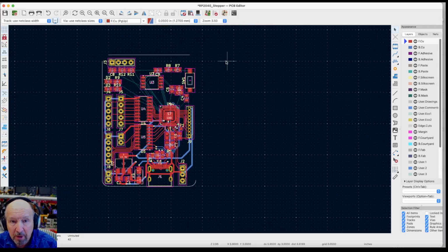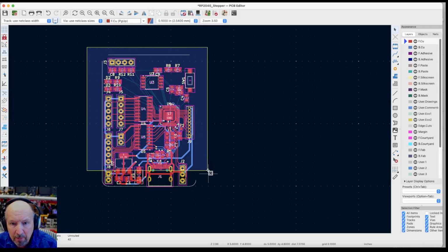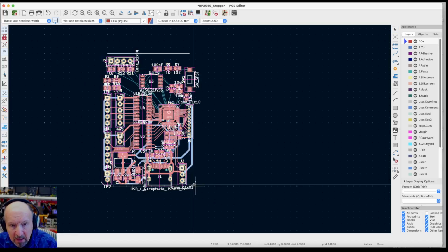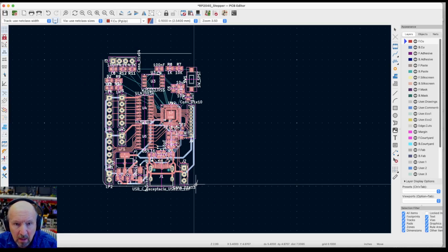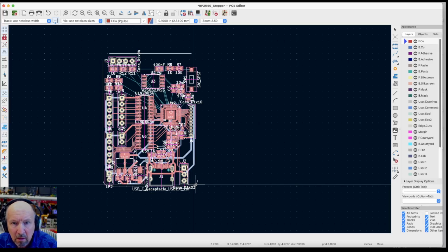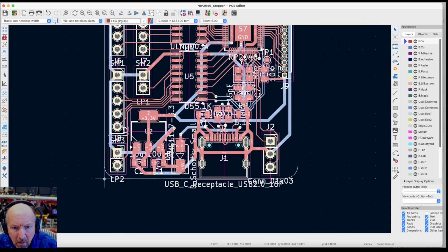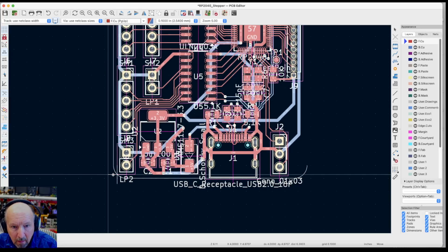So I want to shift this whole thing over 1/10 of an inch. Let me just flip my grid to 1/10, swipe it all, do an M key to say I want to move it, and I just move it to there. How are we not still where we want to be? See, that doesn't look right yet.